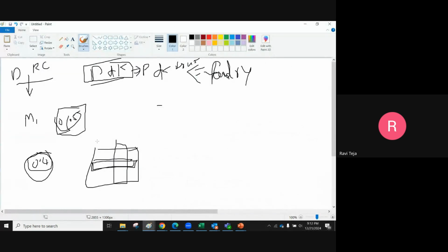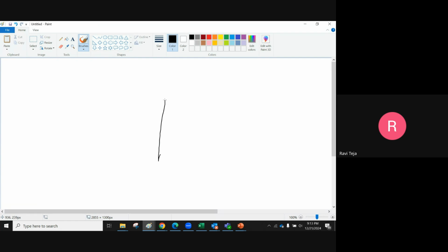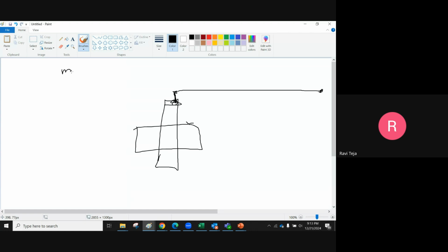And then we have antenna violation. Antenna, in the sense, if there is any long metal connected to the gate, then at the time of manufacturing, while etching, there is some charge accumulated on this metal.